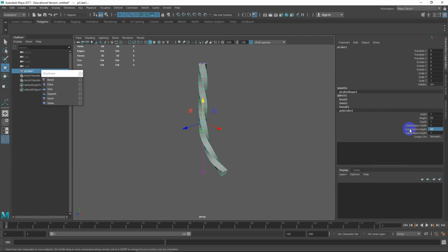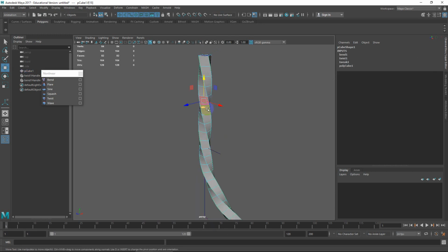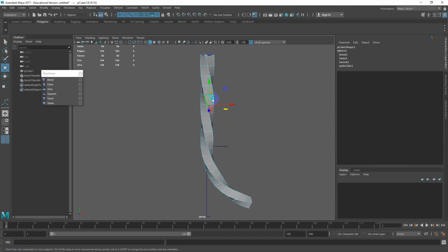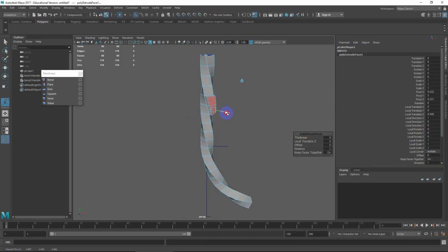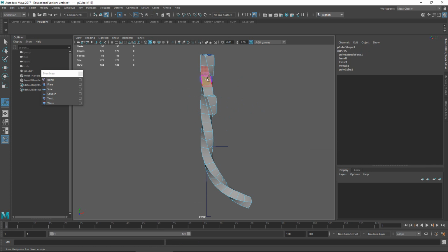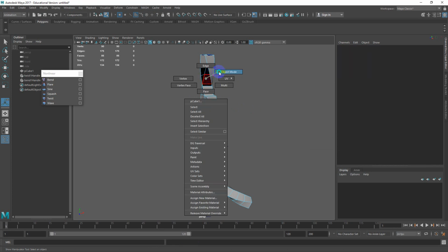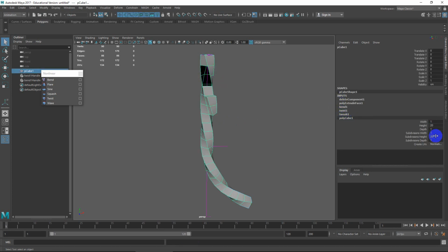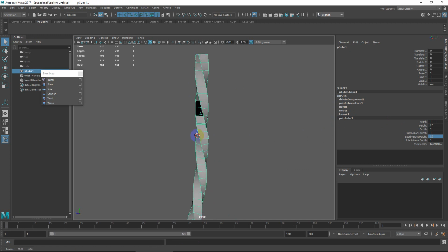So it's important to keep these nodes active and alive when you first start building stuff so that you can quickly jump up and down. Just keep in mind though, if you start doing direct edits, like if I do an extrude face and so on, or delete something else, not that I would necessarily do that, but if I go back and change this subdivision count to, I don't know, 25, it could push this off somewhere else.